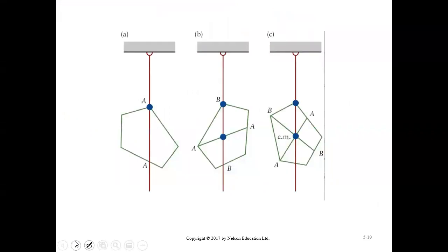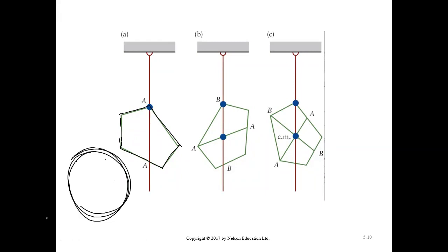Right, now how can we find the center of mass or the center of gravity experimentally, not from the equation? Let's say we have an object, a sheet, in some arbitrary shape. It is not symmetric. If it is a symmetric object like a circle, made of the same uniform material like aluminum, and someone asks you where the center of mass is, what is the answer? Center, right? The geometric center will be the center of mass, where you can balance it. But if the object has an irregular shape like this, mathematically finding it is one story, but experimentally we can find it.